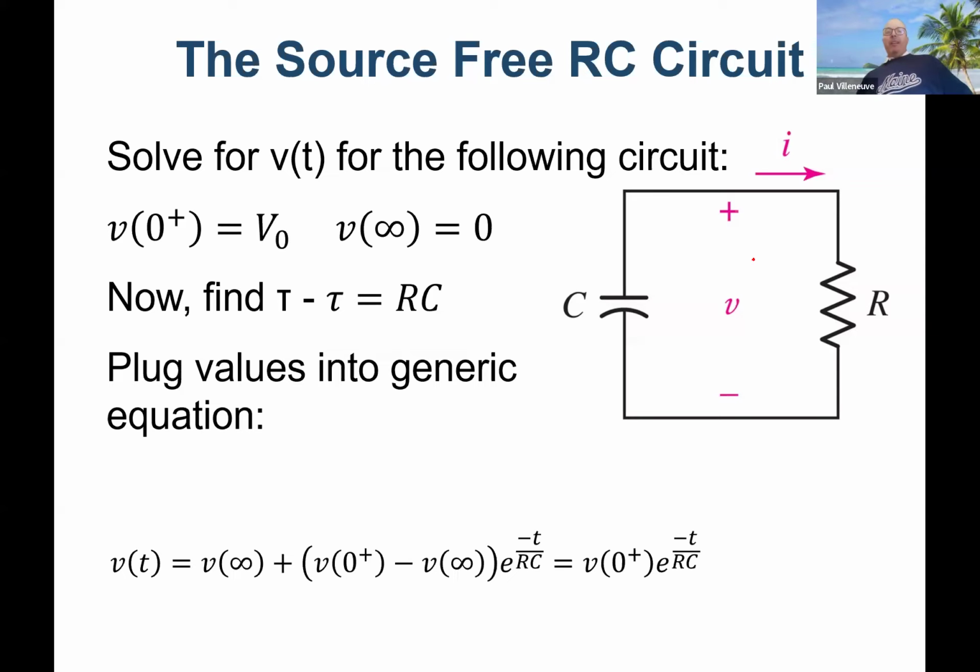Sort of, but do you remember when we did the equations for capacitors? What'd we say? VC is equal to 1 over C integral of I dt, correct? And when you integrate something, you cannot get an instantaneous change. You can't go like that, right?